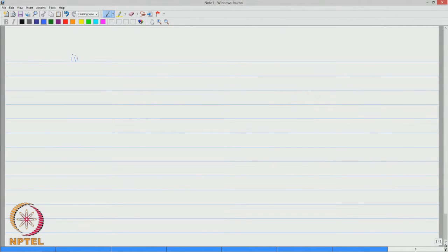The next parameter could be the center height of the fireball. Again in meters, the height of the fireball is given by 0.75 of the maximum diameter of the fireball.